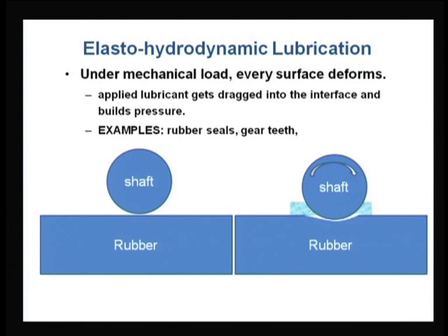That is helping us. The deformation and the subsequent viscosity increase both act together and can give us a very favorable environment for the tribo interface, where the friction will not go to a very high value because there is a change in the film thickness itself.